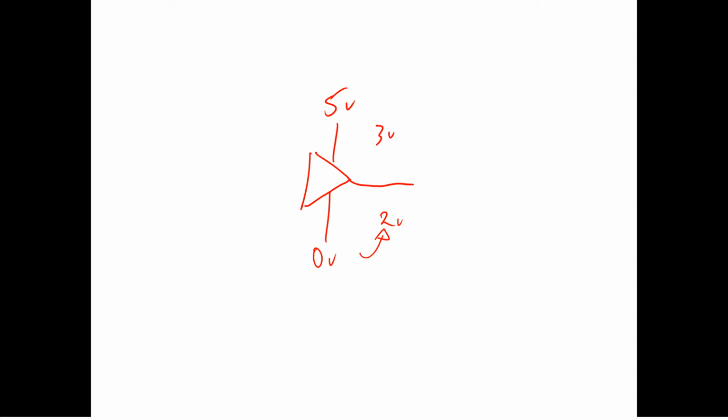There are a few ways. One is that if you can get a negative voltage, if you can tap off your battery pack, you might be able to get like minus 2 volts here, or minus 1.5, for example, if you just take one of the batteries at this side. And so now the minimum voltage you could go to is going to be closer to 0. It's not quite going to be 0, but maybe you get 0.5 volts.